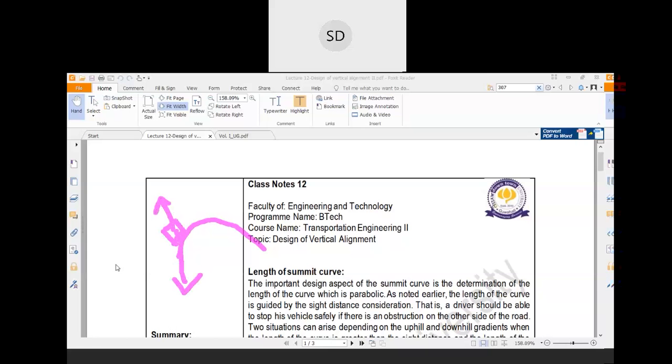For this reason, some component of the weight of the vehicle will be nullified by the centrifugal force. So for this reason, the pressure exerted on the vehicle axle and tire would be minimum.